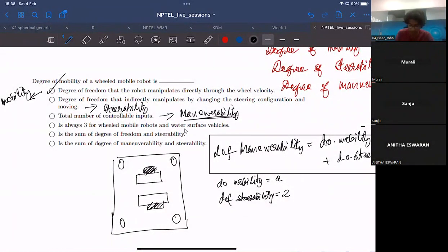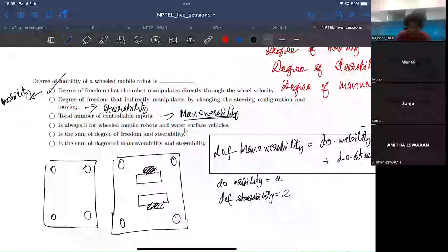If you want to control the wheels independently, you would see in the upcoming sessions, probably from week 2, regarding the generalized wheel kinematic model, you would require one of these wheels to be aligned in this configuration and the other in some other configuration, so that it can basically rotate about its own axis. Can you see what I'm getting?